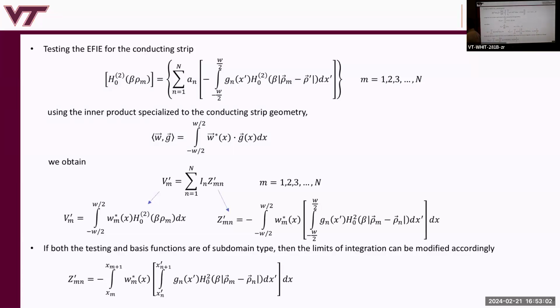There's a lot of challenges with that, though. I mean, you have to somehow unhomogenize it at the end and do a unit cell design and come up with actual geometry of printed circuits that can emulate these impedance sheets that we will use the integral equations to design. And then there's a lot of other challenges. Metasurfaces in particular have subdomain unit cells, which means the impedance sheet could be anisotropic in each of these unit cells. So there's a ton of degrees of freedom.